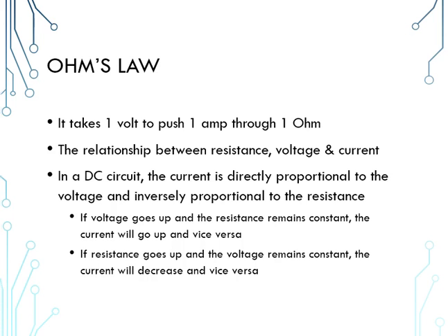A loose connection, corroded terminal, corroded wires, a loose light bulb, a switch or something else in that circuit that has been in use for a long time and has some wear on it and has changed value, an increase in the resistance. So by knowing these relationships as a technician, you can save yourself a lot of time and also save yourself from having to do the math.